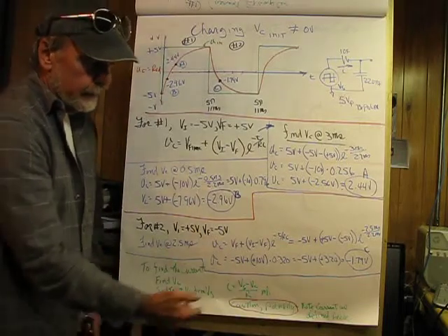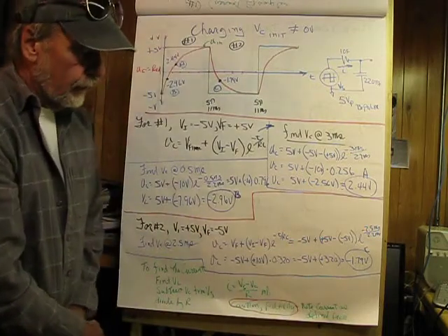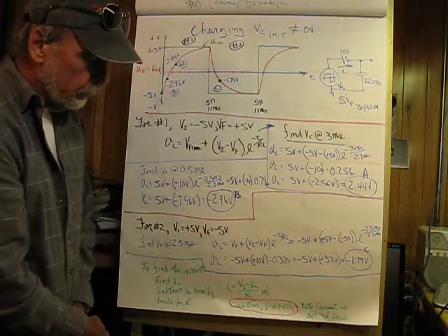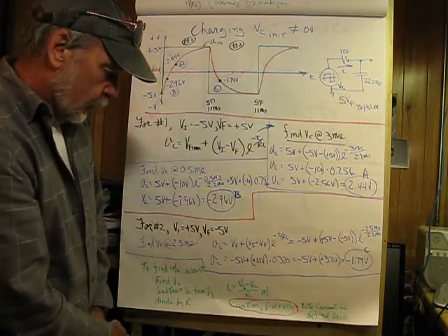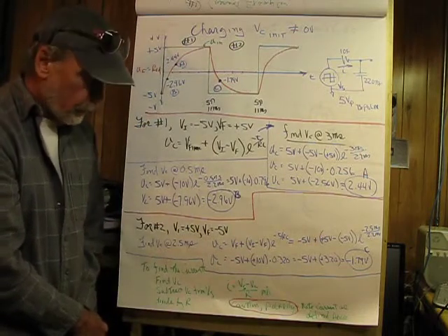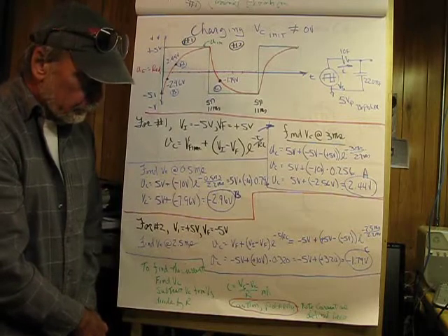Next, we're taking e and raising it to the 2.5 milliseconds divided by one time constant, which is 2.2 milliseconds, and that ends up giving us a value of 0.320 times 10 volts, order of operations.